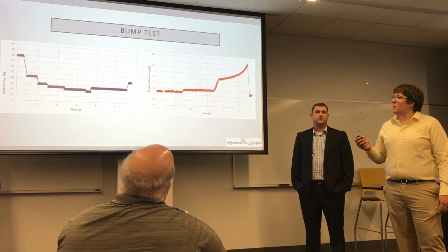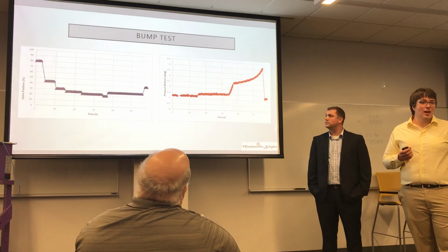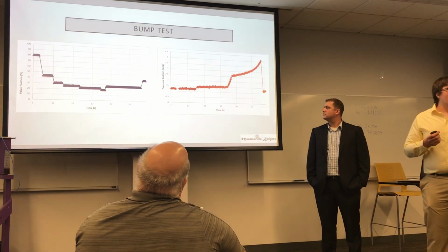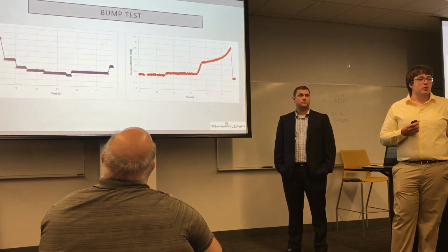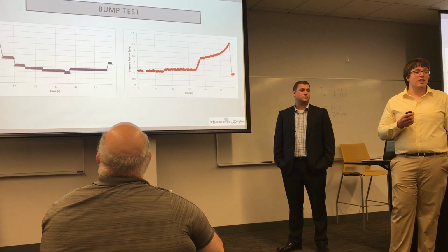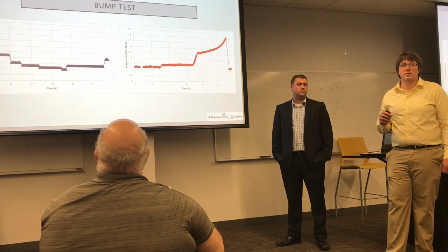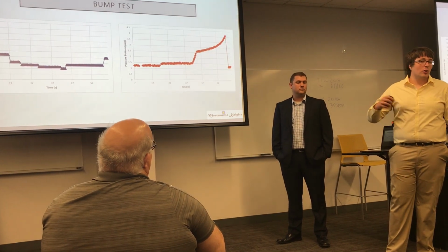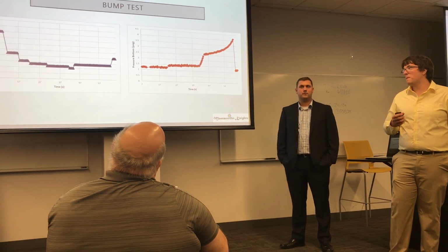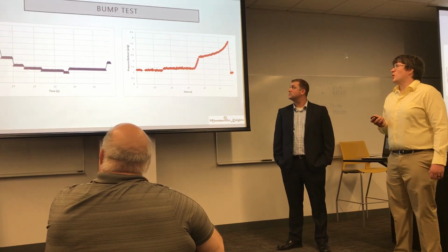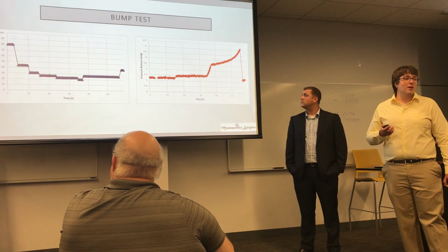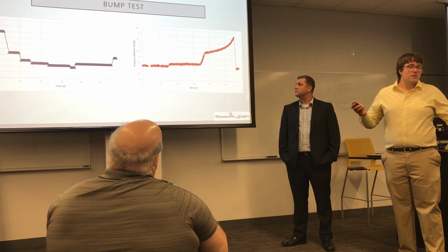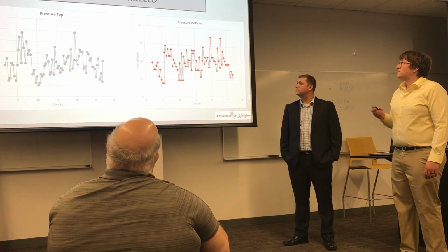Also, at about 19% valve position, you see the pressure spikes. Now we need to be very careful not to overshoot into this almost closed region, because we could actually make the system worse by doing this. We don't want to have the pressure rise and release rapidly due to our controller always overshooting, right? To make matters even worse, from about 100 to 30%, we have virtually no control with our gate valve design. So just one of the things that happen.